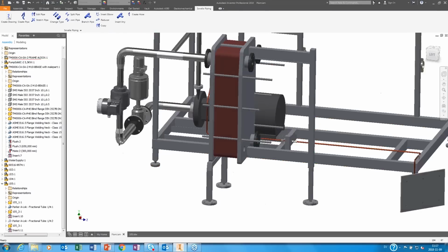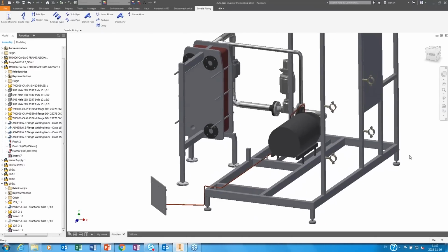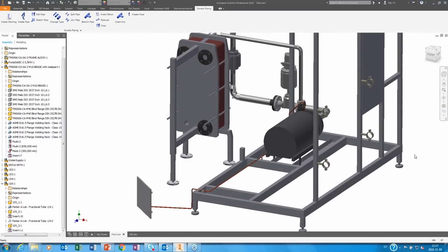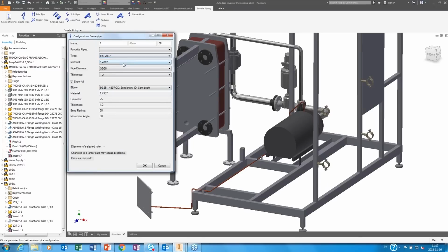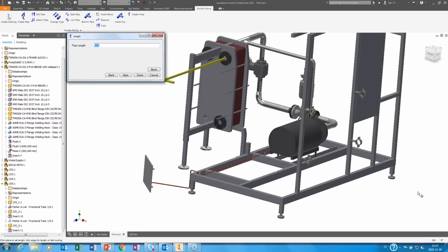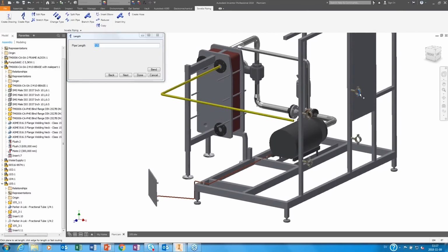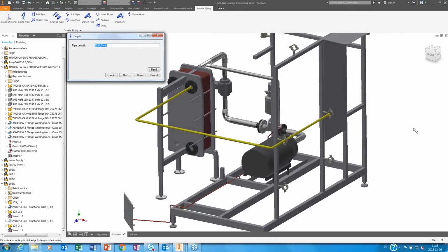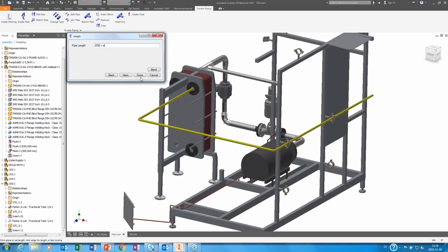Now I will also show you a bit if we want to draw many pipes when we know the center distance, the CC distance. So I will create a new pipe. I select, and I just draw it small now because it will be easier to see. We can change the size afterwards. So I just choose one and I want to go to the frame, maybe -30, enter. I want to go in this direction, I press enter, and now I want to go through my pipe holders, and maybe I will want to end somewhat here and say done.